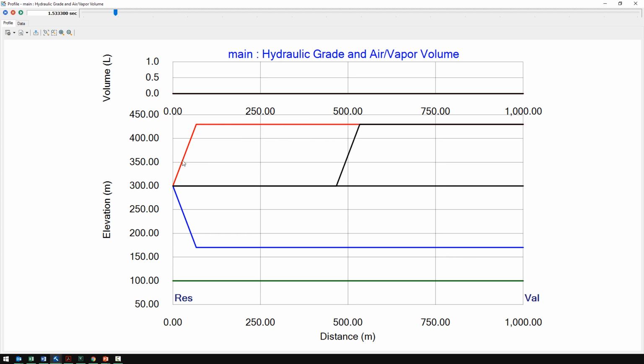So you can see it has decreased. First we increased the pressure, and that wave has moved all the way to the upstream end of the system, and it's reflected basically back down to the initial pressure. And that's going to then propagate down to the end and all the way down to the valve. And we're at only 2 seconds into the simulation. So you can see with the wave speeds that you typically have in Hammer or for a transient simulation, these are happening at very, very small time scales.